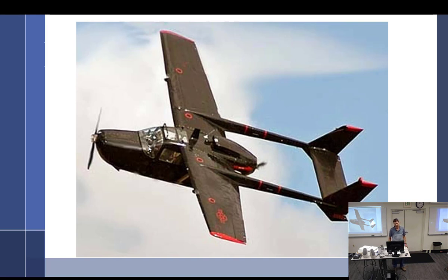In fact, while we're on the subject of gear, there have been many incidents of mechanics working on Cessna gear. We have to do gear swings every annual on an aircraft, so like any good mechanic, they'll get their jacks out and jack it up and make sure the wheels are nice and clear, and they'll hit the hydraulic pump pack. It pushes down on the aircraft, lifts the aircraft off the jacks, then moves it forward a couple of inches, right, so that the jacks, because the jack point is the wing, go right through the wing. That's how you get the fuel out.